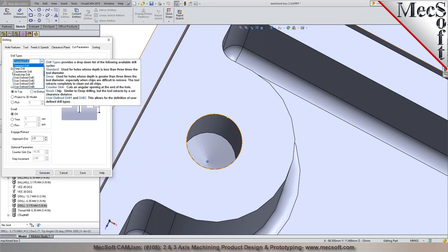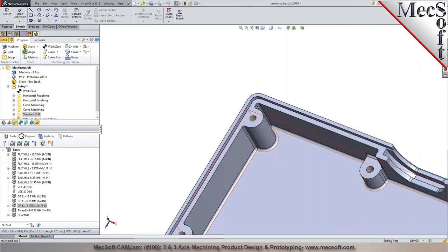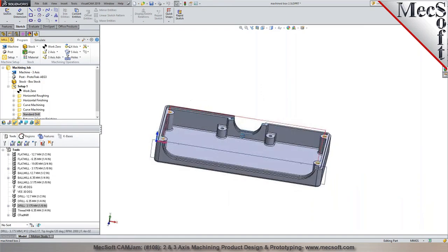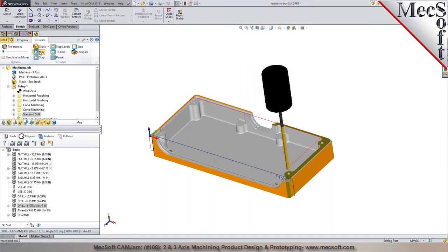You can do standard drill, deep drill, countersunk, chip break. So we have all the drill cycles built into it. And if the controller for some reason wants to output a linear motion, we can output it as a linear motion as well. Okay. What was the project to 3D?